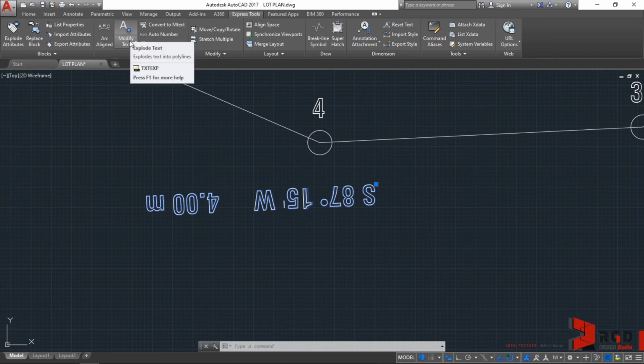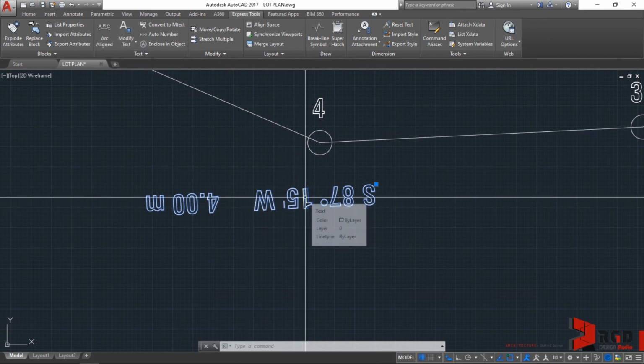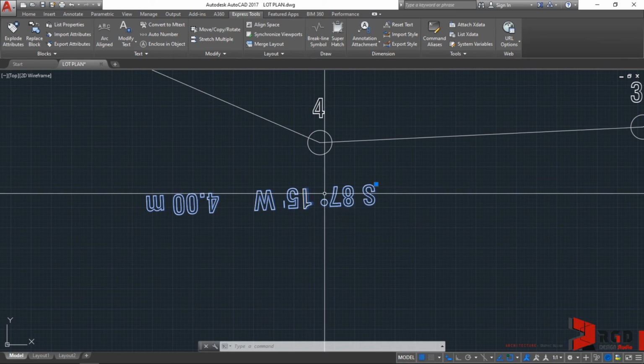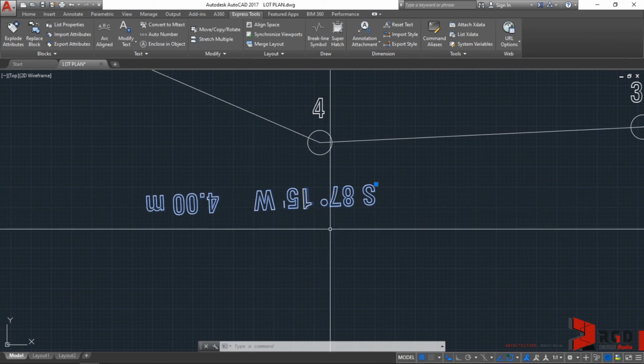And our concern now is regarding this awkward looking, or I mean unreadable text. By the way, in our convention of proper labeling and dimensioning, all text must be able to be read from the bottom of the paper and at the right side of the paper. I repeat, the convention for labeling and dimensioning is that all text or dimensions must be able to be read from the bottom of the paper and at the right of the paper.